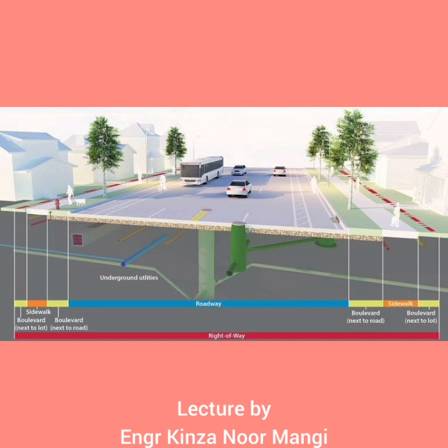Now coming towards the right of way. Right of way or land width is the width of land acquired for the road along its alignment. It should be adequate to accommodate all the cross-sectional elements of the highway and may reasonably provide for future developments.